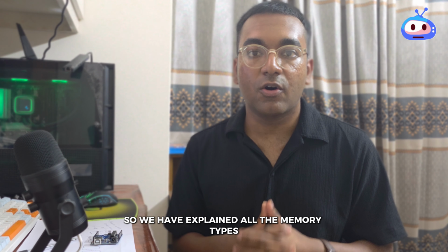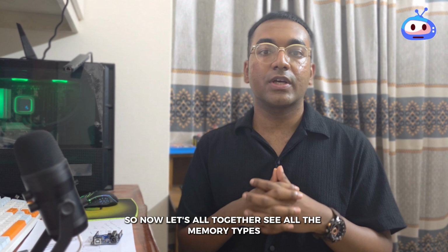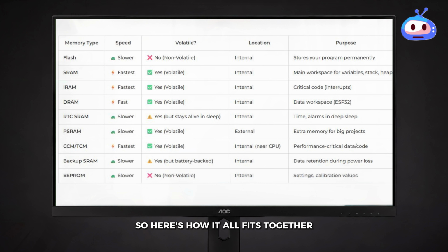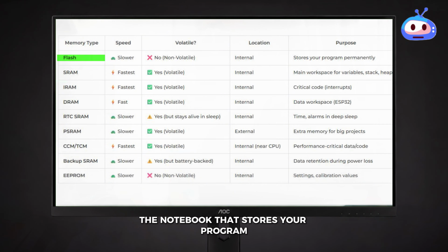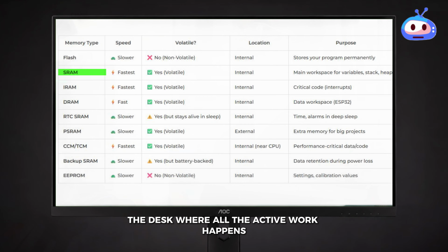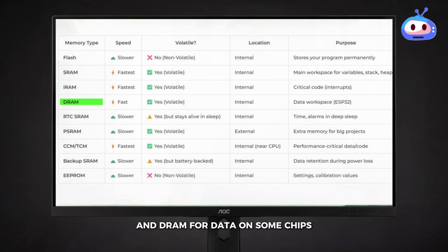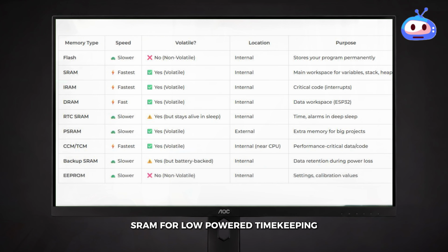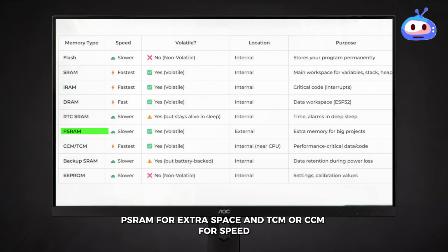So we have explained all the memory types. Now let's see all the memory types together so you can compare each one with the other. So here's how it all fits together. At the top you have flash, the notebook that stores your program. In the middle you have SRAM, the desk where all the active work happens, split into IRAM for code and DRAM for data on some chips. Then you have specialized memory types: RTC SRAM for low powered timekeeping, PSRAM for extra space, and TCM or CCM for speed.